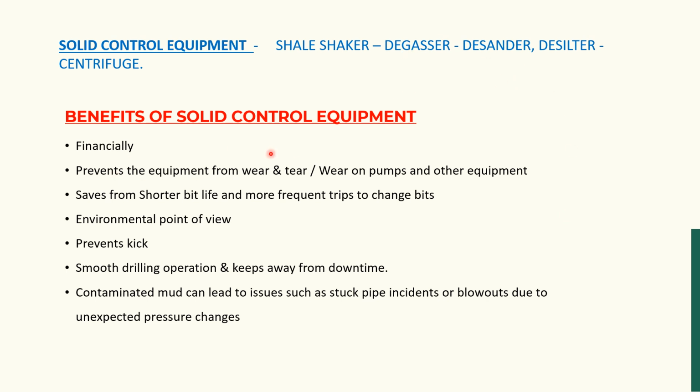And what are the benefits of the solid control equipment? The benefits are many. Financially, it prevents wear and tear on the pumps and other equipment, and saves from shorter bit life and more frequent trips to change bits. From an environmental point of view, it prevents kicks, gives a smooth drilling operation and keeps away downtime. Contaminated mud can lead to issues such as stuck pipe incidents or blowouts due to unexpected pressure changes. So these are the benefits.